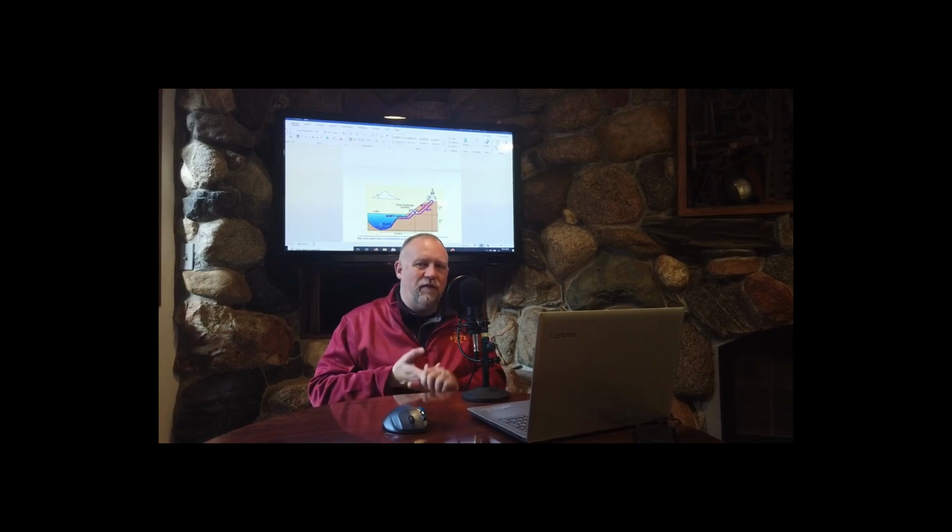Okay, so let's pause there on heat pumps. Remember, some tips for the class. Remember to keep in mind advantages and disadvantages as I'm comparing them to other systems. There is no perfect mechanical system. All right. And what's the best system changes with the size of the building, the physical location of the building, how much space is available, how important energy efficiency is to owners, and really changes with costs in energy.